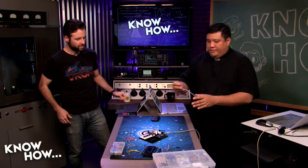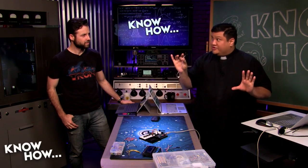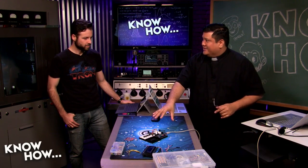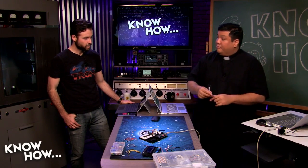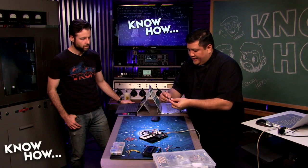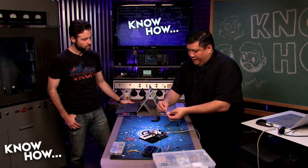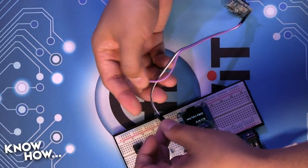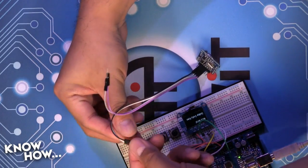All right. So this is also an I²C device, so I need to hook it up to the same bus. We got a little messy last week in where we hooked it up. This week it's going to be much more clear that we are using the exact same pins. So the first thing I need is power. On this one, black is for ground and white is for voltage. So I'm just going to go ahead and plug this in like so.